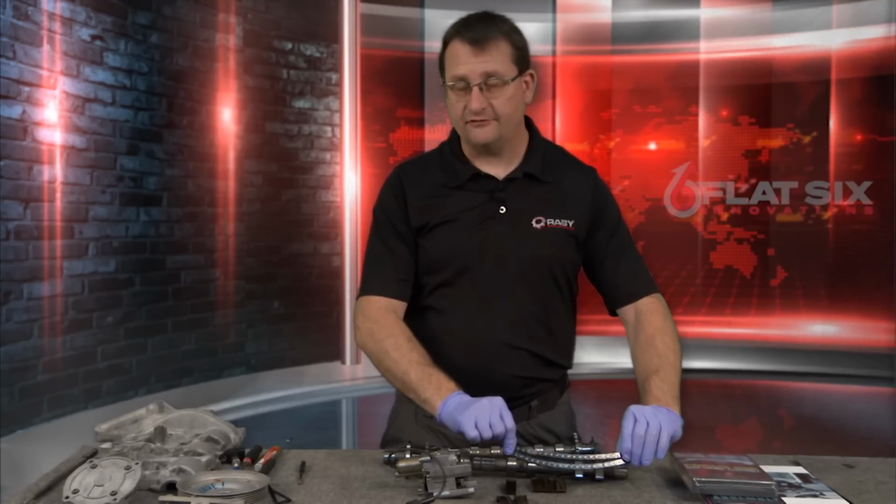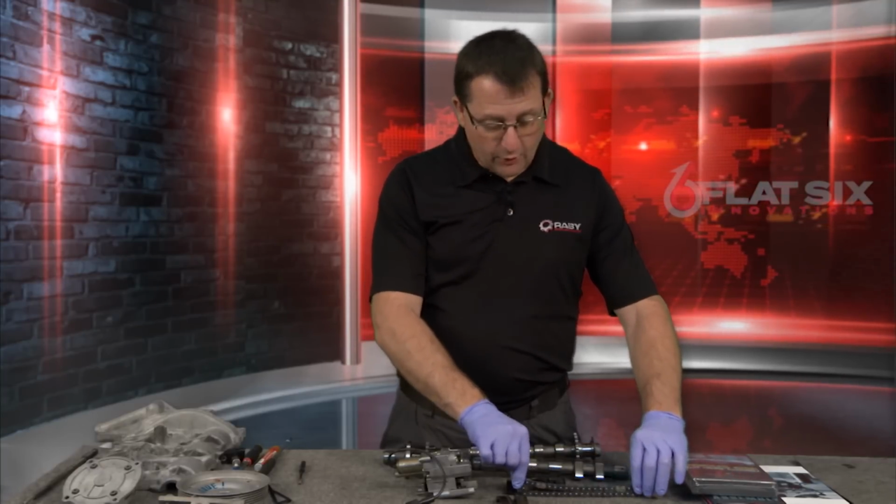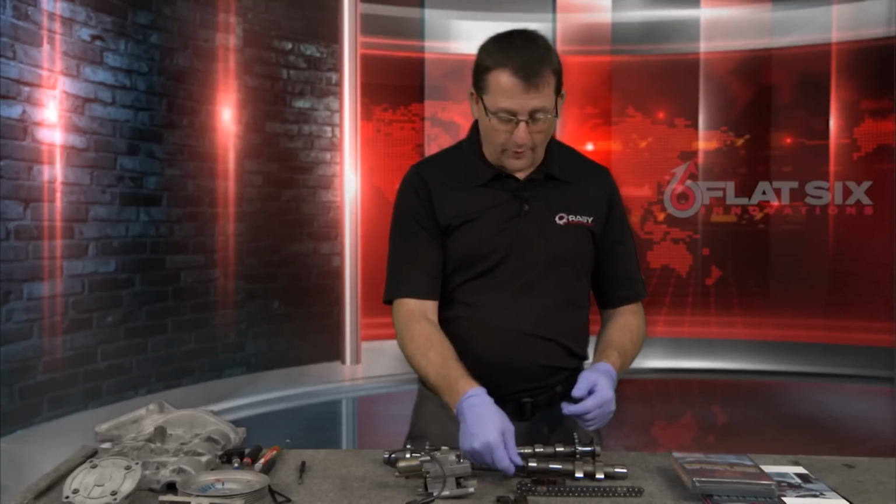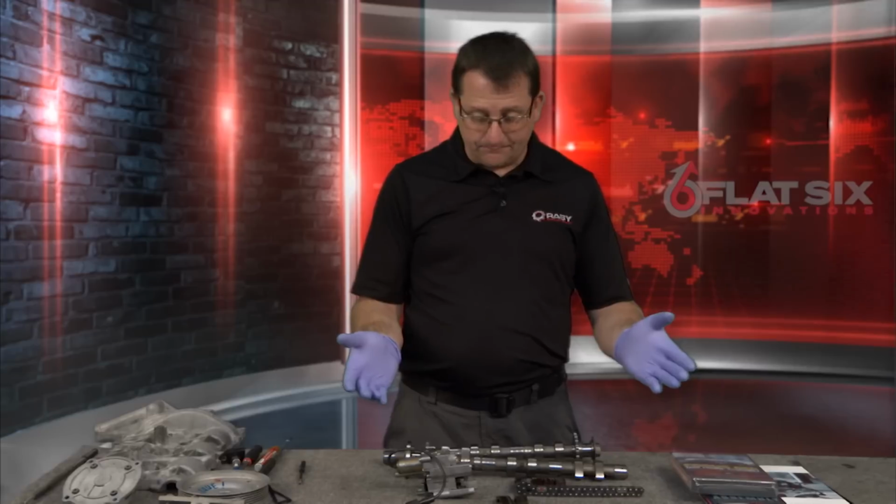You want to replace these chains. They are cheap. You also are going to buy a small kit of these parts. Porsche sells the new wear pads as a pair, so you'll have to have two pair for the engine, basically. So one pair does one bank of cams. And once you've got that, clean everything up nice and well. Obviously, cleanliness is next to godliness.